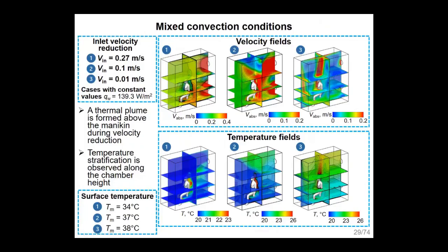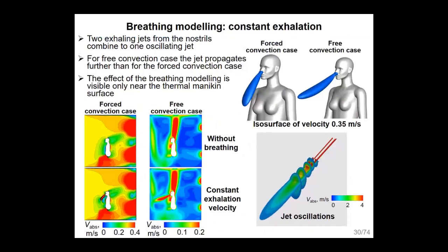So for the mixed convection conditions, you see we obtain the thermal plume here, and we obtain the global circulation here in the domain. Unfortunately, we don't have experimental data for these conditions, but this is a very important problem. I just mention it here because we have a large amount of output from this particular problem of free convection.